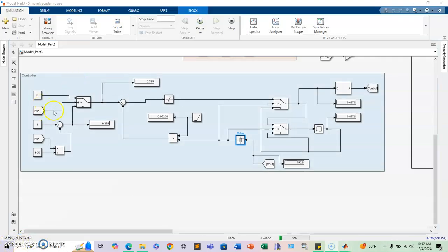See how the voltage right now is switched on the second part, because this is the initial value, and see how my ramp is adding a little bit to the control modulation. So this is like having a PID, but not really with a PID. With a PID, in my case, I couldn't tune it in real time, but this auto-tunes itself in real time. That's why I have the ramp, and I'm having the feedback on the left, and I'm having the relay to cap it off to the output that I want. But I'll explain more on it later.